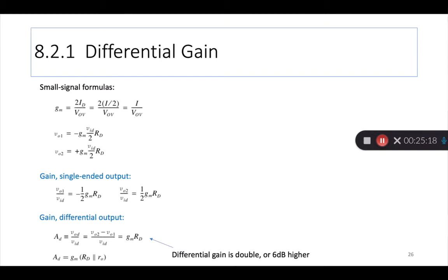Again, in this entire analysis we have ignored common mode signals. We are only focusing on differential signals. We are assuming there is no need to include common mode because the devices are perfectly matched, and the power supplies are also completely complementary.